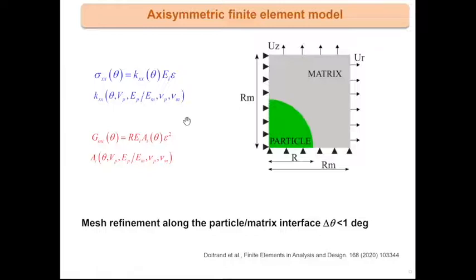So it is necessary to perform a study with increasing refinement of the mesh, and in practice, the discretization of the angle along the interface will be lower than 1 degree. I recommend these recent papers, where we define practical considerations for using the coupled criterion, either from an asymptotic point of view or from a finite element point of view.